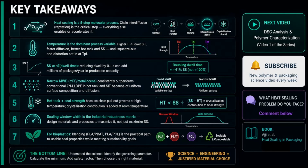7 things I want you to take away from this video, directly from the science. 1. Heat sealing is a 5-step molecular process. Step 4, interdiffusion, builds the bond. Step 5, crystallization, locks it. If either step is incomplete, the seal is incomplete. Every machine parameter and material property maps to one or more of these steps.